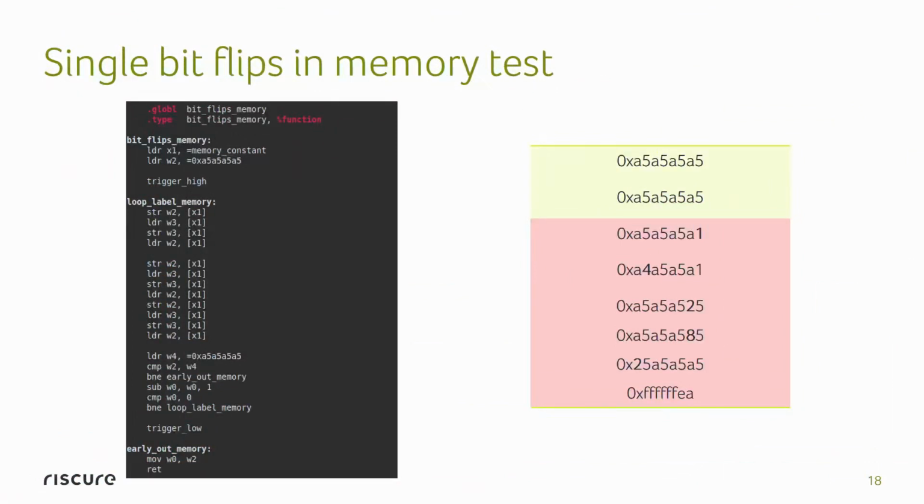So in the case where the device is operating normally, you have not done any fault injection, it will give you back at the end that exact same A5, A5, which is an arbitrary choice of constant. And then using the hardware setup we showed earlier, we will deliver our glitch at some point during this loop, which is just reading and writing that variable. So what we want to see is how can we affect the operation of the device in a way that's useful to us.